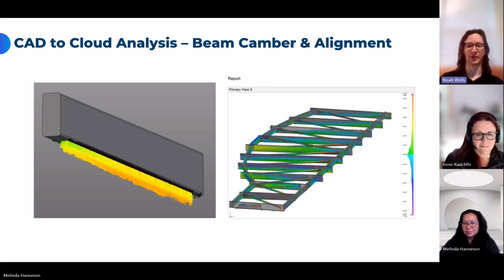Here we were looking at surface deviations earlier of just flat surfaces, pretty simple, right? But here we can see we ran that same surface deviation on all of the surfaces at once of this beam network underneath the bridge. You can see the histogram there showing a really nice color gradient of all the different deviations. We can see certain areas it's a little bit higher, some areas it's a little bit lower. We can see specifically those cross beams seem to be a little bit out of tolerance, but considering that we built this intentionally to be out of tolerance, that's to be expected.